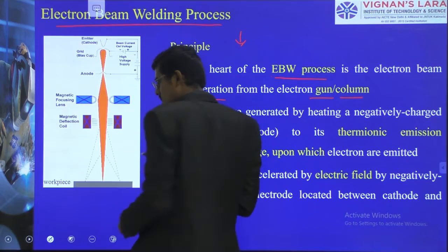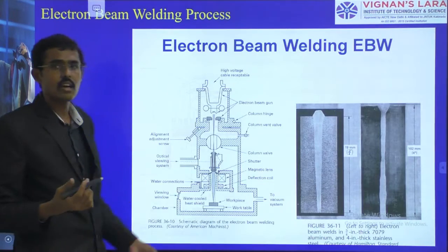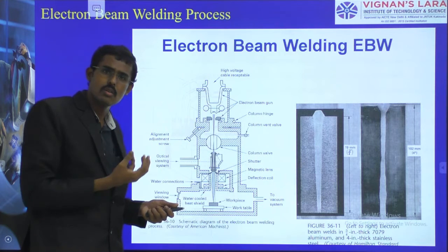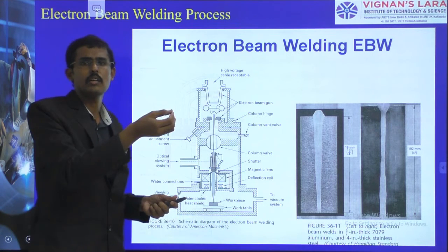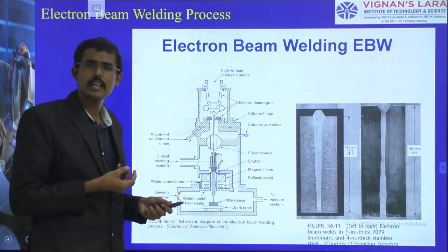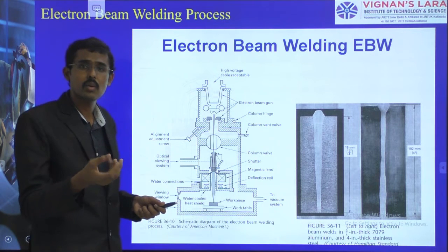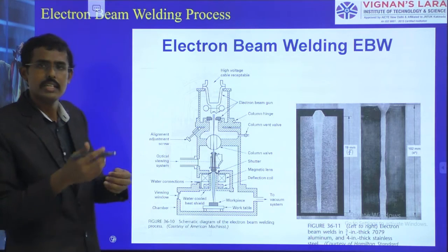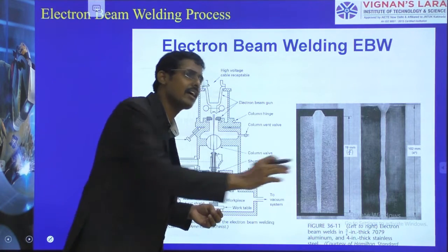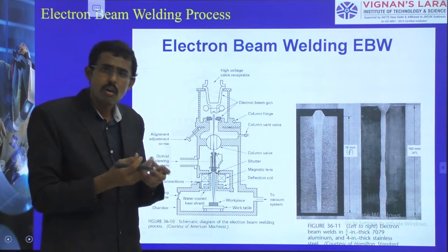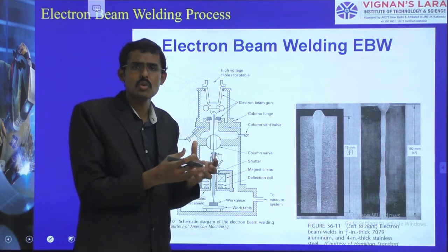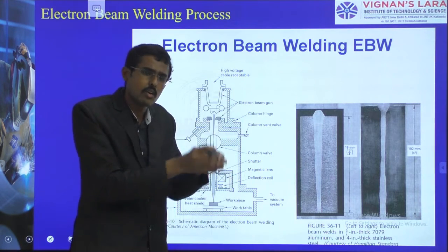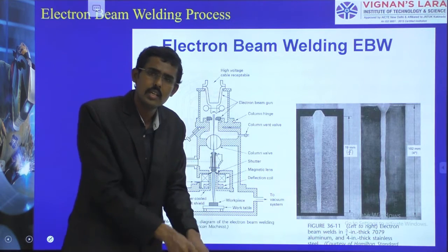We are going to generate electrons, as in the electric arc welding process, where the electron flow also takes place from negative to positive. We have taken care of direct current electronegative and direct current electropositive. A similar pattern of supplying electrons with high velocity is done here, but with a tungsten source, emission of electrons, and the electrons travel directly towards the workpieces.